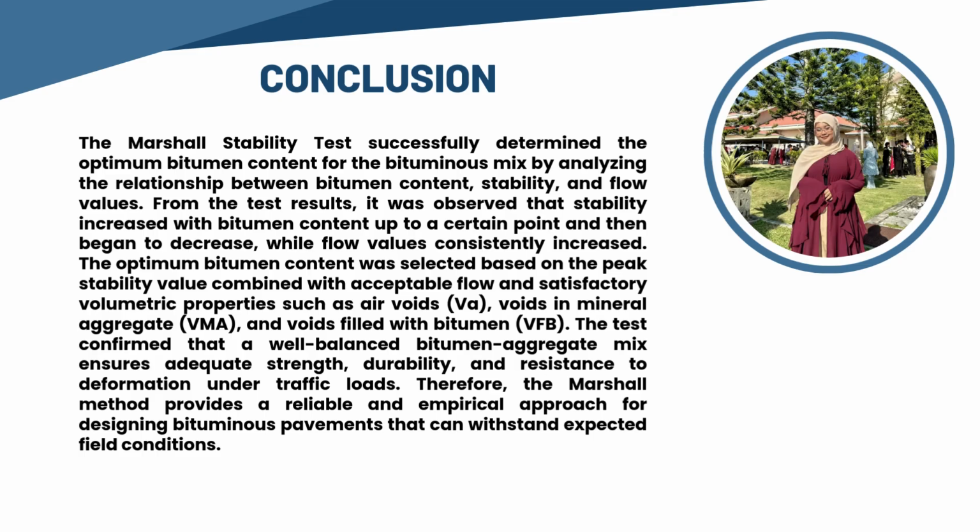So for the conclusion, the Marshall stability test successfully determined the optimum bitumen content for the bituminous mix by analyzing the relationship between bitumen content, stability, and flow values. From the test result, it was observed that stability increased with bitumen content up to a certain point and then began to decrease, while flow value consistently increased.